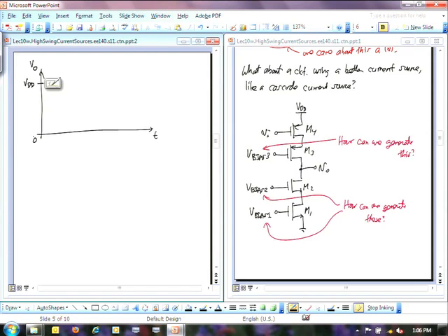And so in order to get my maximum swing, I want to bias my V naught, which I'll call capital V naught, the DC bias point, right in the center of this. Because if I put that right in the center, then that allows my swing to be maximum here without going nonlinear. And the reason for that is if I look down this way, the lowest this voltage can go is the sum of one overdrive voltage for device 1 and another overdrive voltage for device 2. Okay?